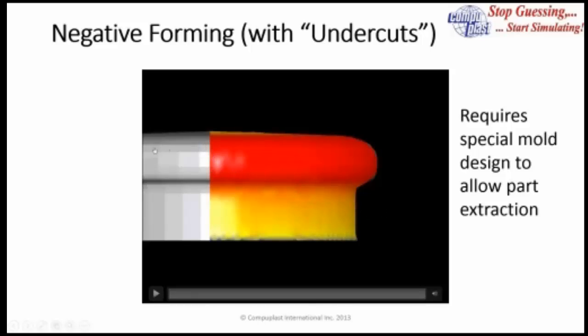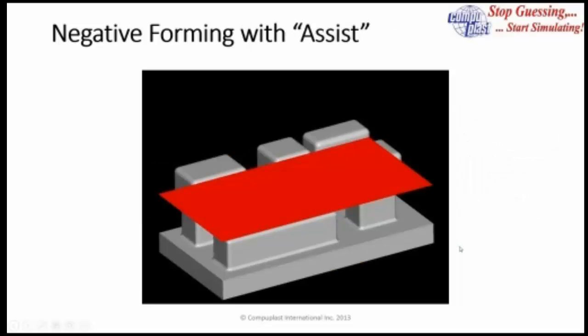Now, you'll notice that the whole part isn't filled. We always take advantage of symmetry whenever we can in a simulation. So if you have a symmetrical part, if this part I believe is circular, we only need to do, let's say, 1/4 of the part to do the simulation. So I'll show more of this later on.